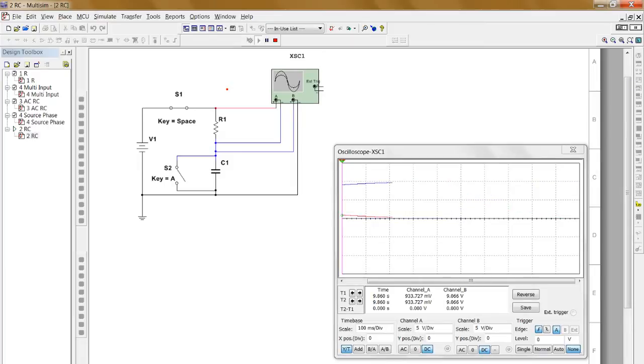Well, what that means to us, I'm going to do that one more time as I talk. What that means when the voltage on the resistor goes down, since the voltage on the resistor is directly proportional to the current in the circuit, then we know that when the voltage on the resistor is going down, the current in the circuit is going down. I'll do that one more time. There it is. As the capacitor charges up, the current in the circuit is going down.